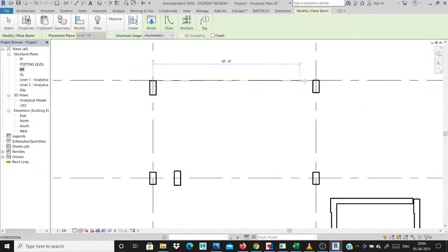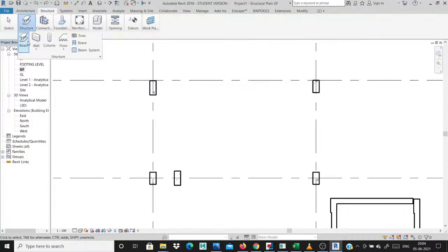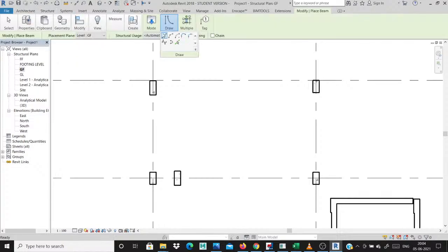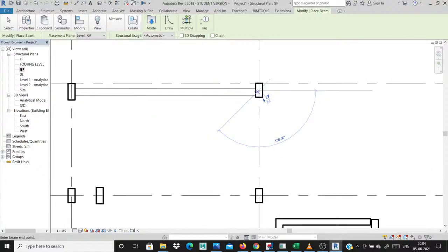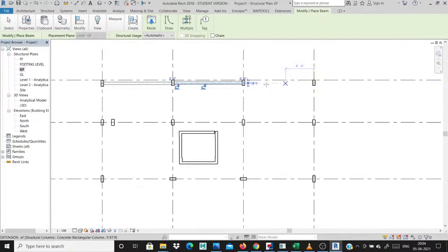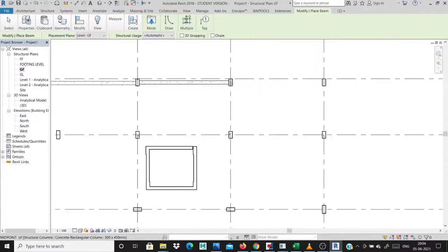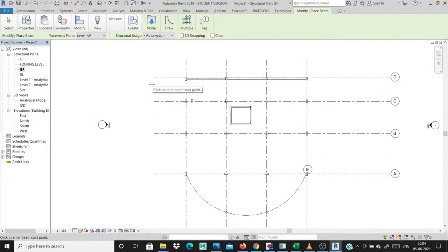See, this one is going outside, it's totally wrong. In this method I simply go to beams, I need this area, simply take this option. You take this center line option, you click this, automatically you take this center option also. Then center to center, right, you click this center, then this one, then click this center, then click this. Now it's automatically created the ground beams.